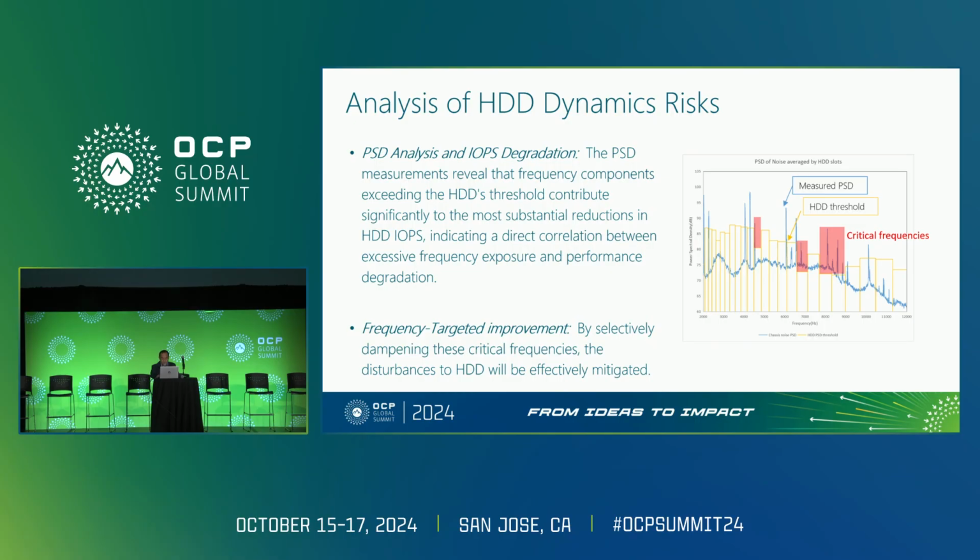Further analysis has proved that there is a direct correlation between excessive frequency exposure and performance degradation. If one can selectively dampen these critical frequencies, the disturbance to HDD will be effectively mitigated.